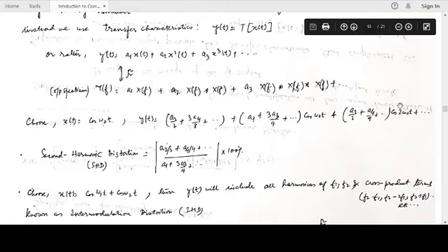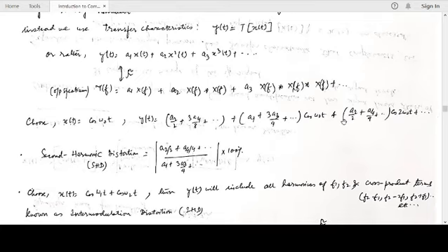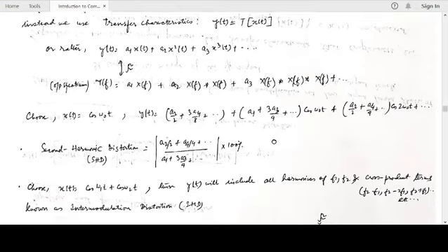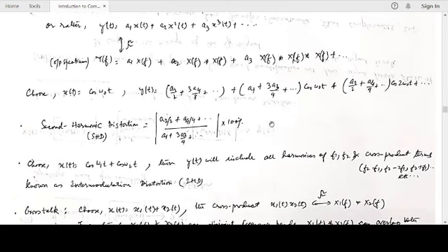And we have cosine 2 omega naught, which is coming from a2 by 2, a4 by 4. So we have taken x square, x cube and x to the power 4, a4 x4. If you expand them and collect the corresponding terms up till, let's say, 2 omega naught t, you arrive at this expression. So we have certain parameters for nonlinear distortion.